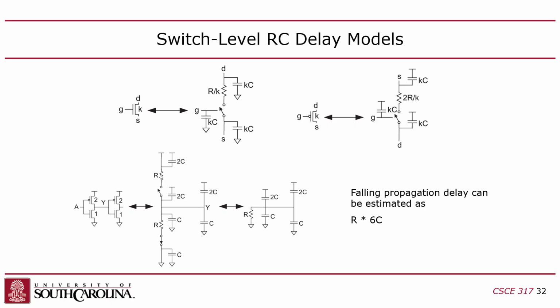this is the equivalent circuit. Now, again, keep in mind, this is the NMOS resistance, that's the PMOS resistance. And remember, they're both R, even though this is size 2, because you have to size up the PMOS by a factor of 2 to get the same resistance as the NMOS, right? So it's kind of confusing, but that's how it is. PMOSs have to be twice the size because the holes are just weak mobility, slow charge carriers.